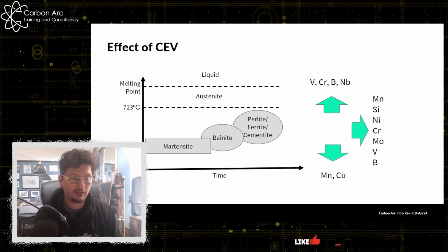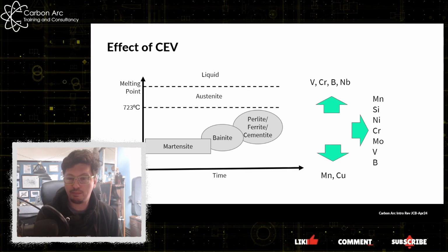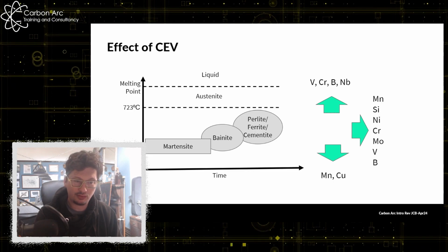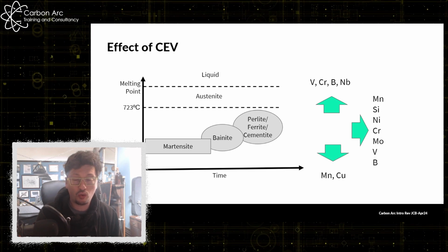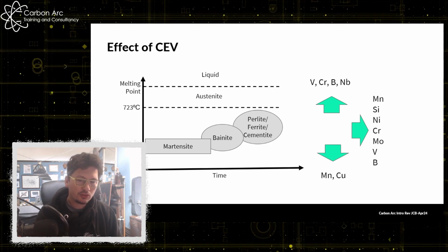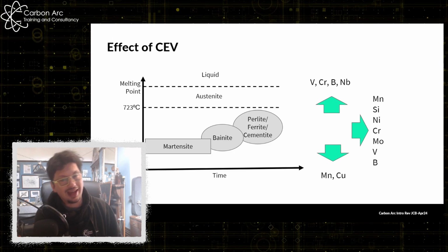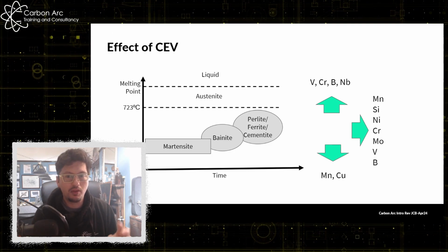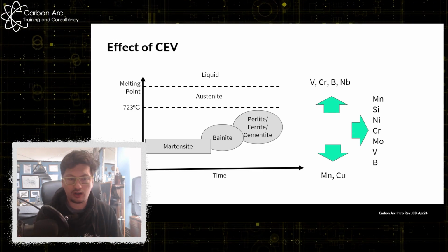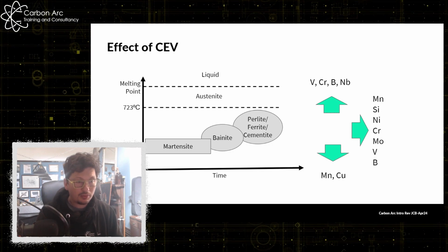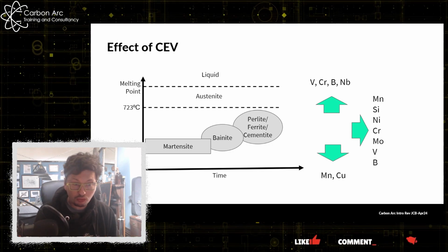carbon there, definitely, but then our manganese, which is a big adjuster and a big thing we add to steels to increase strength. You see you've also got the common ones like nickel and chrome. But some things which are non-metallic, like silicon, which is used as a deoxidizer, that is all going to make the weldability less. So it's going to be harder to weld. Some things move it down and some things move it up. And you can see that some of them cross with each other.